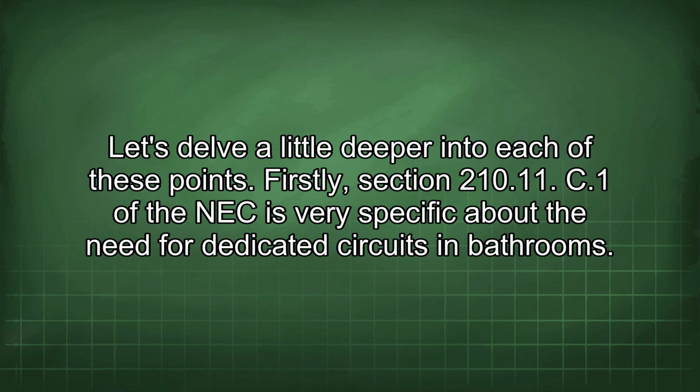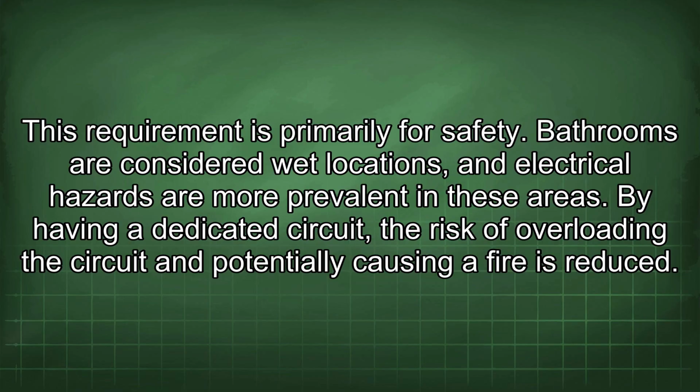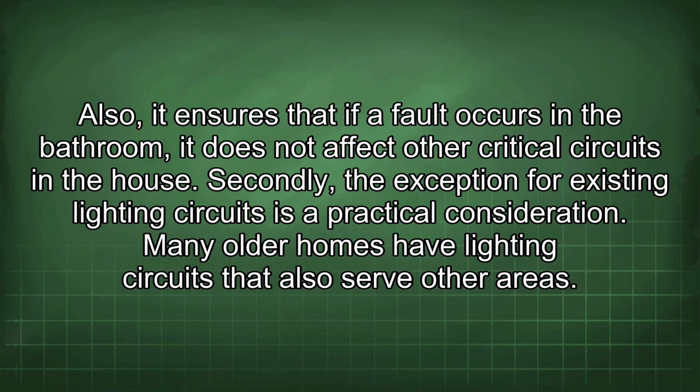Firstly, Section 210.11(C)(1) of the NEC is very specific about the need for dedicated circuits in bathrooms. This requirement is primarily for safety. Bathrooms are considered wet locations, and electrical hazards are more prevalent in these areas. By having a dedicated circuit, the risk of overloading the circuit and potentially causing a fire is reduced. Also, it ensures that if a fault occurs in the bathroom, it does not affect other critical circuits in the house.